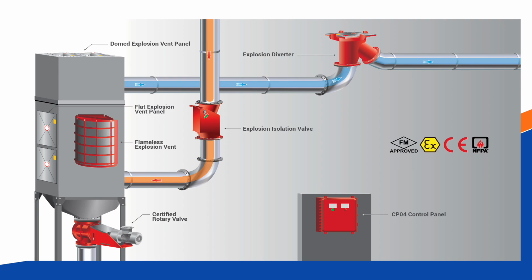When it comes to explosions, NFPA calls out for explosion venting and isolating between vessels. So basically, if you have interconnected vessels, you want to provide protection in between each vessel that's connected. Next slide, Andy.